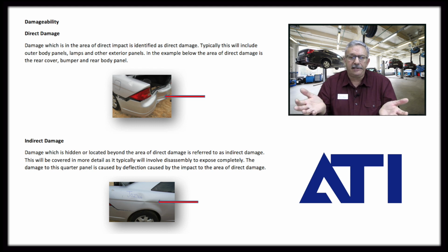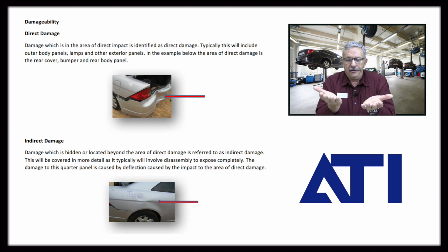And if you've got multiple estimators or repair planners in your facility, they need to calibrate. You want everybody on the same page with every issue. If one's going to charge X amount for corrosion protection, the other's got to charge the same amount, so that you've got a standardized process. When the insurance company comes in, they're not going to the one who charged them the cheapest amount last time and saying, they set precedent here. No, we say this is our process for charging for a particular operation. This is how much it's going to be. We're going to be consistent and repeatable in that.